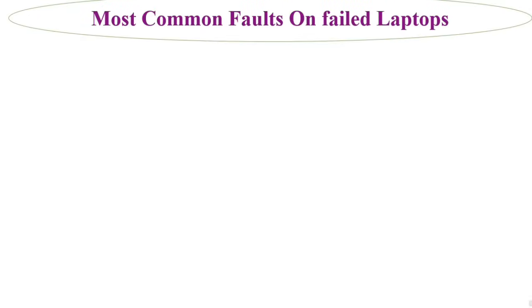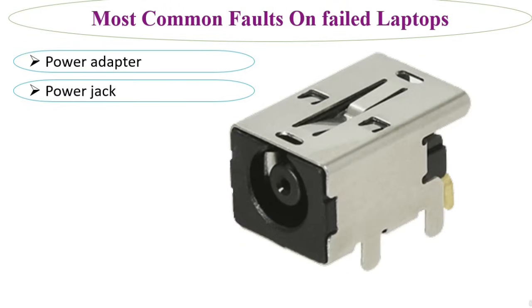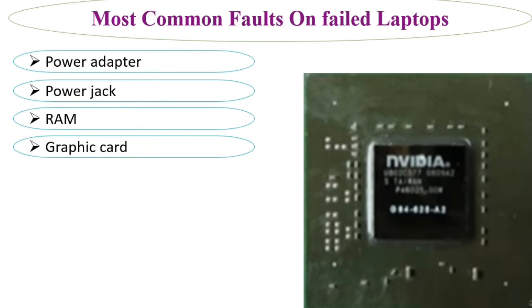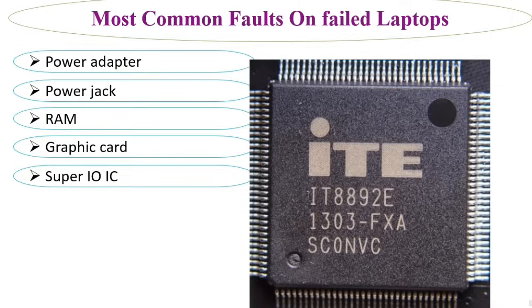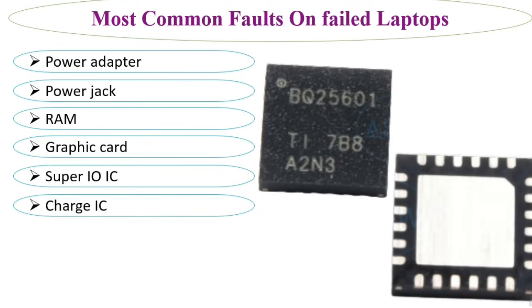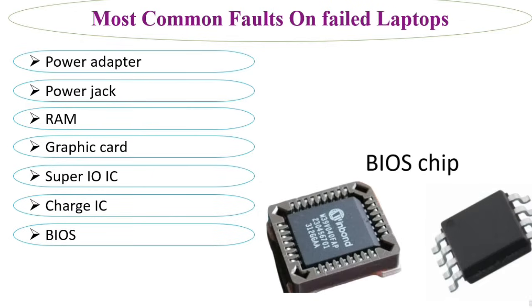Hi, in this course we're going to see the most common faults on failed laptops. We're going to see the power adapter failure, the power jack faults, the RAM or random access memory faults, the graphic card faults, the Super I/O IC or Super Input Output, and the charge IC faults. I'm going to show you how to diagnose the charge IC, and the BIOS or basic input-output system faults.